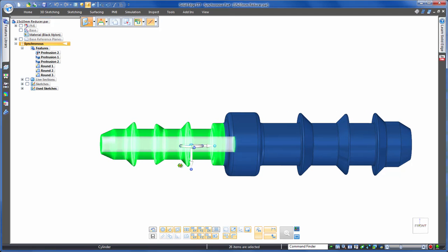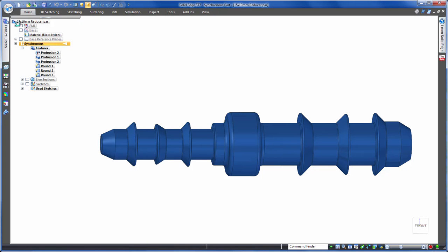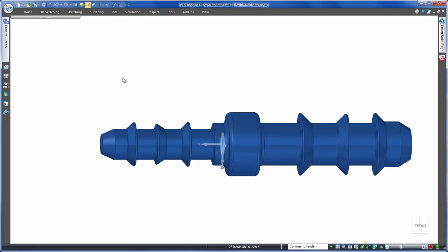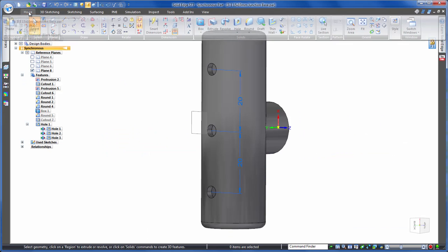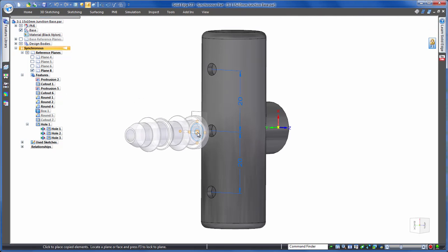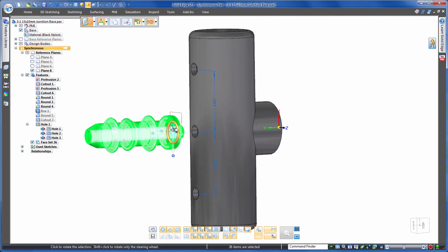Oh, and notice that we're moving what we call the steering wheel to a specific position. This is our main control for synchronous technology, and here it'll help us locate the detail in our new part. Then simply click copy, or use the Windows Ctrl+C shortcut. Back in our custom fuel adapter, we just paste it in, again using the Windows shortcut Ctrl+V if you like.